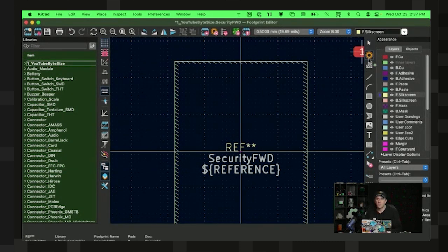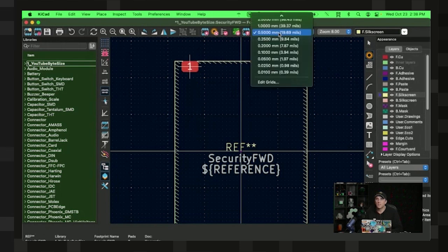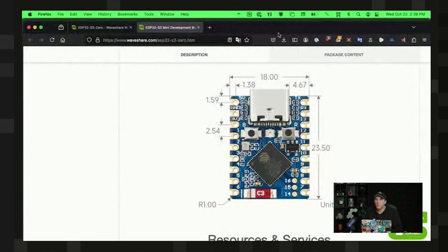So here I can select the pad. I think I can select different pads, but this happens to be the type of pad I'm already looking for. So that's fine. You can see it's just like a flat pad and I can modify these to be different if I want to. So I'm going to also put my pad basically all the way up against the edge. And again, I need to make sure that I can snap to the correct distance. So this is 2.5. This needs to be 2.54.